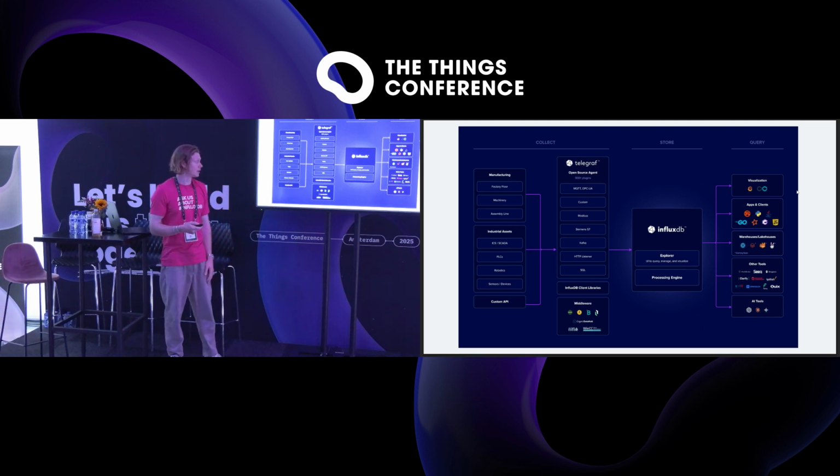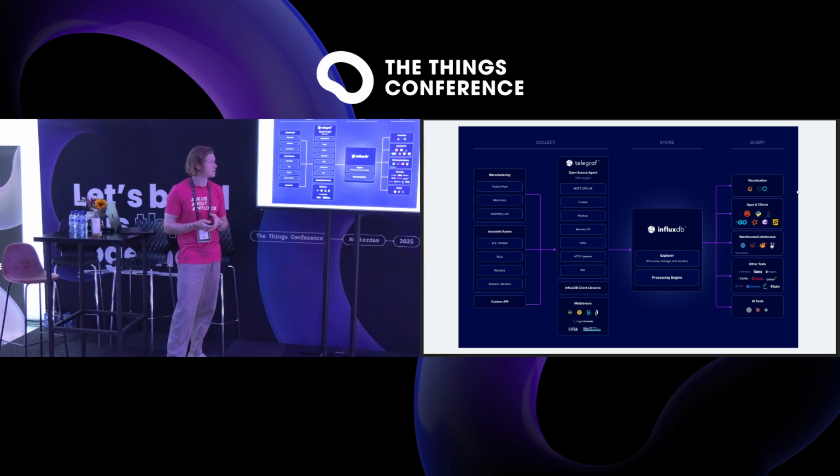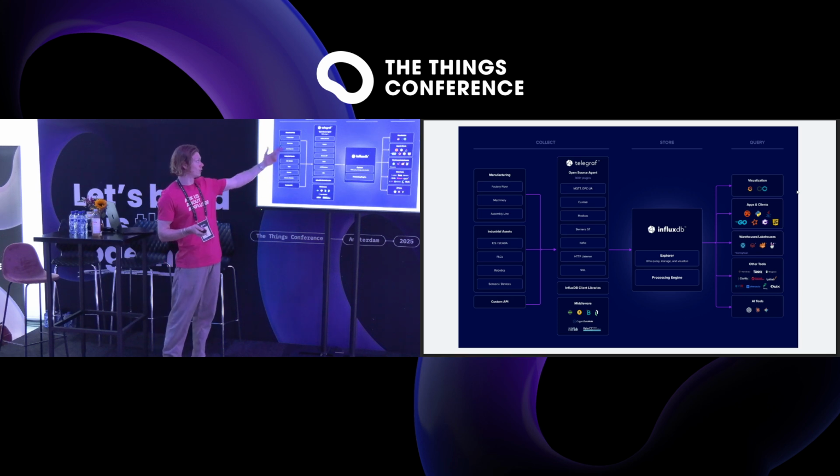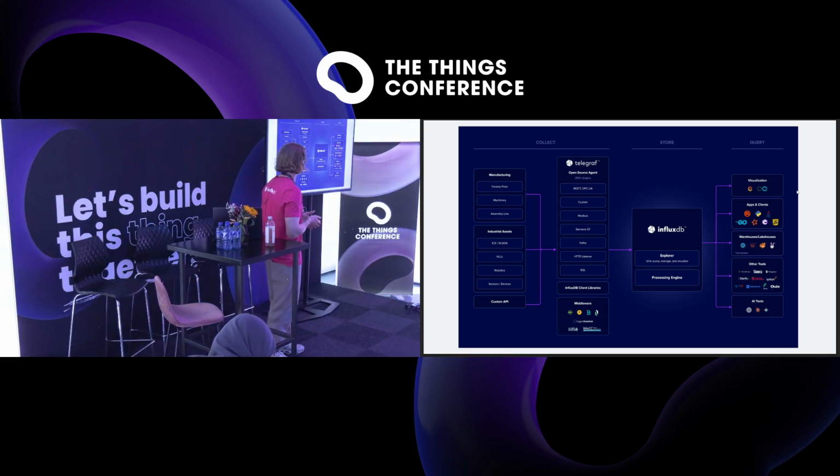Middleware. So for example, solutions like Kepware, HiveMQ, HighByte, Litmus all have built-in plugins for Influx. So if you use one of those to scrape industrial data, they can output it into Influx in an optimized way. And of course, Telegraf, that's a solution we developed. It's basically a plugin-driven data collection agent. Plugins for all of the major data sources, IoT ones just to call them out, MQTT, Modbus, Siemens S7, OPC UA, and it packages up and writes data in Influx. Again, open source, actually more popular than Influx.